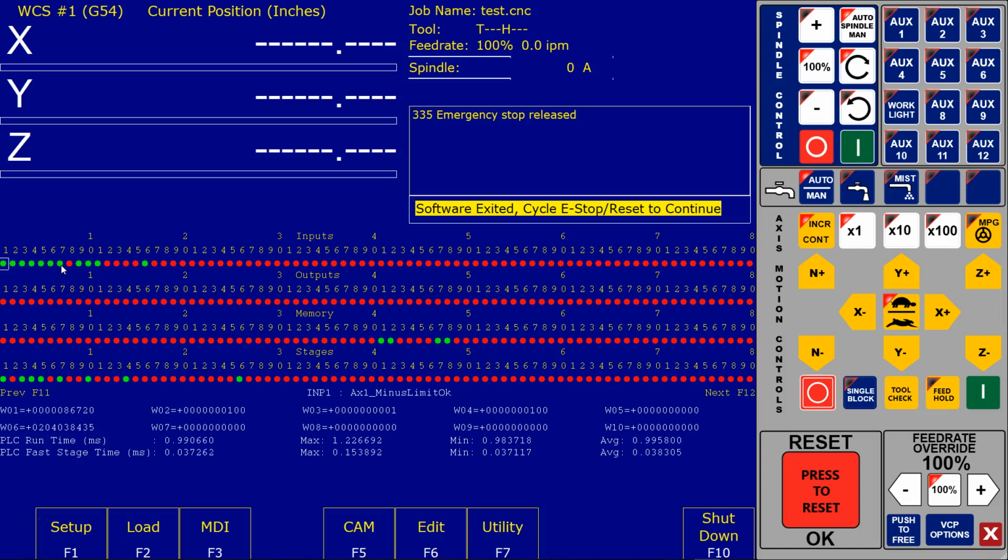But of course, if I just flip the switch here, you can see my input is changing state, going from an open right now to a closed state. Okay. But now I also mentioned that one has the ability to invert an input. So let's say you have something that's wired on there and it's not normally closed, it's normally open. Let's, for instance, say that input number 7 is a normally open input.